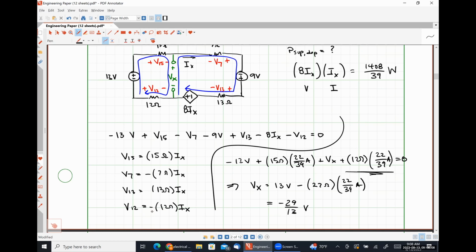So for this class, a lot of what you're going to be doing is deciding which polarity of this particular component should be positive, and which direction the current is flowing. It does not matter what you choose, as long as you're consistent with applying the circuit theory, the math is going to work out correctly to give you the answer that you need. I typically set things up such that my current is flowing into the positive polarity terminal of practically everything I can, because I know that I screw up when I have lots of negative signs mixing things up, and spurious negative signs hurt my brain.